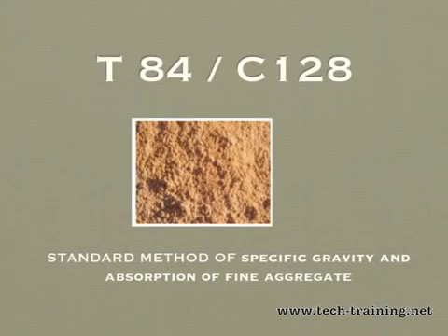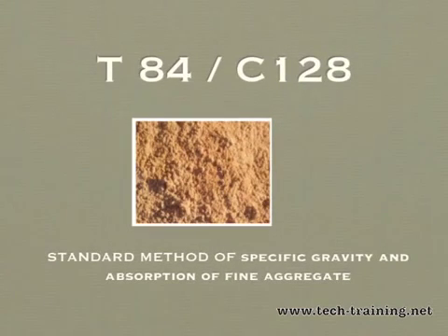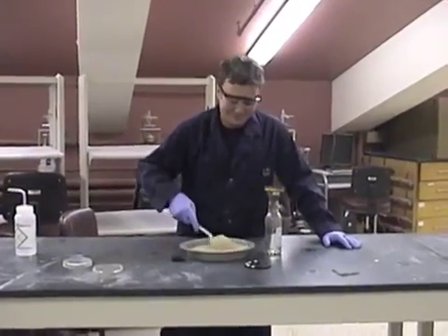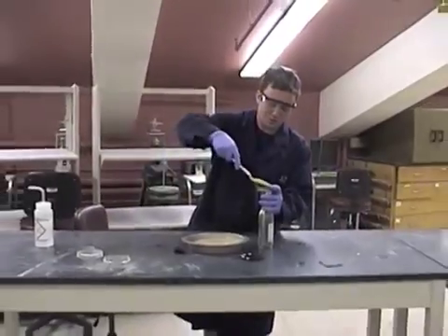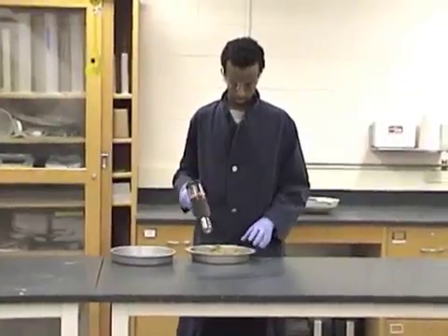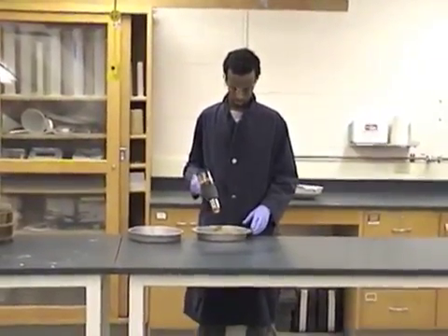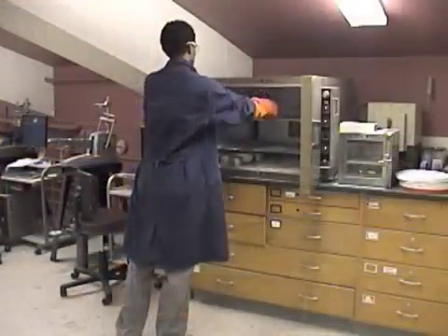When the pores are completely filled but there is no surface moisture, the sand is considered to be in the SSD condition. An increase in moisture or decrease in absorption will change the amount of water in a given concrete mixture.